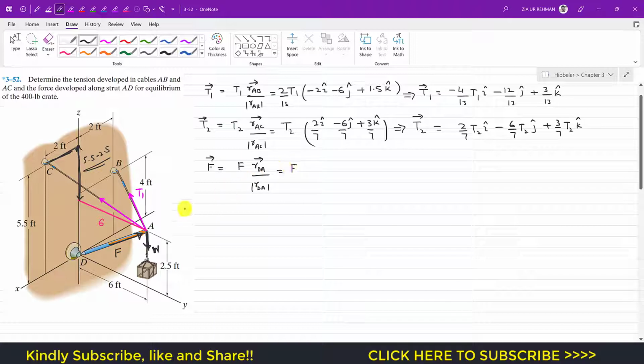So that F, and now we need to move from D to A. So to reach that point A from D, we need to travel 6 feet in the positive y direction or in the positive j. So I will write plus 6j, and then we need to travel 2.5 in the positive k. So I will write plus 2.5k. And since this D and this point A are in the YZ plane, there is no need to travel along the x direction. So this means that the x component of the position vector from D to A is 0. So we need to write this as 0I.